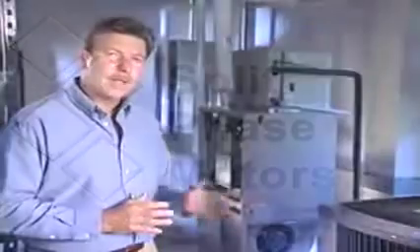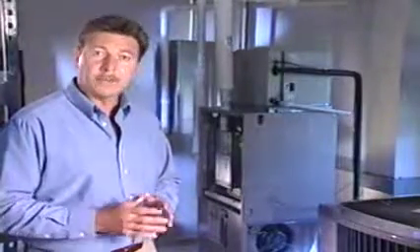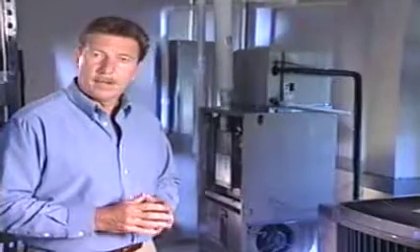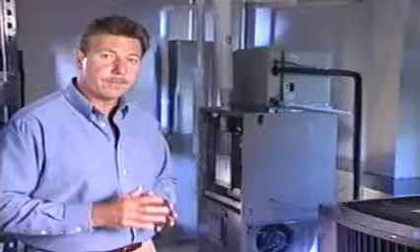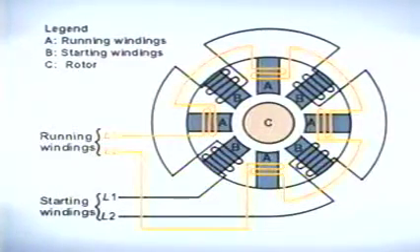The split-phase motor utilizes a phase shift in the magnetic field to create the required starting torque. This type of motor is used for heavier applications because of its higher starting torque. Instead of the shaded poles, a separate start winding is used to create the needed torque. The run winding is energized whenever the motor is energized and keeps it operating as long as power is supplied